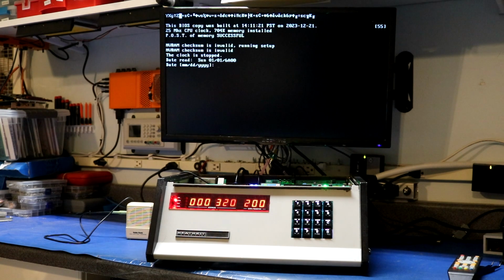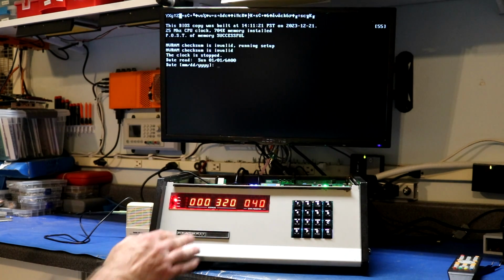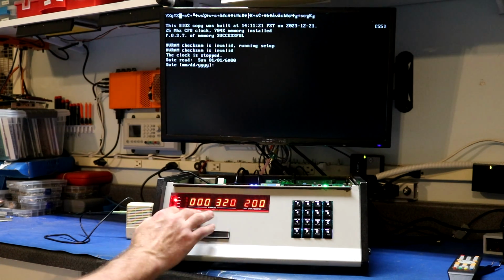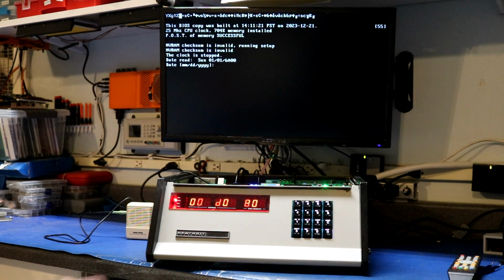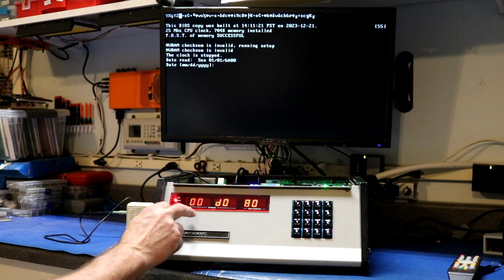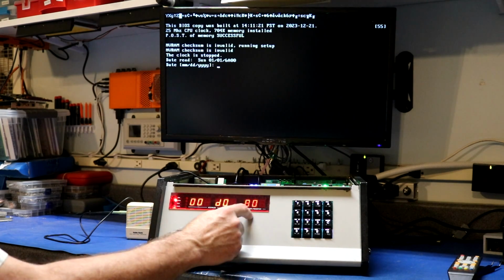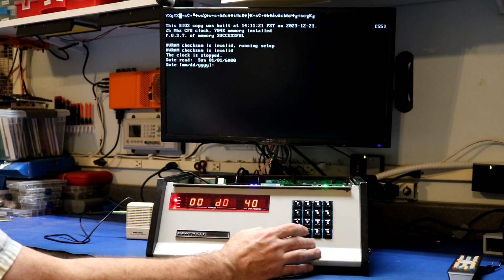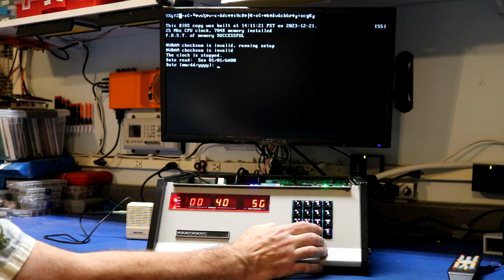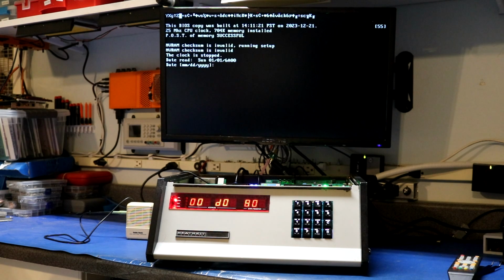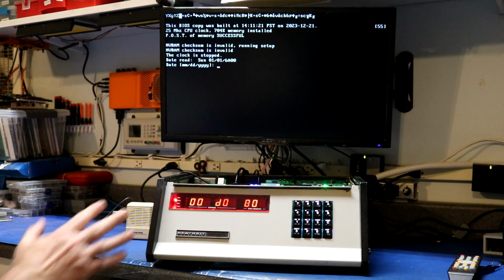I had to implement this from scratch because obviously the one for the 8080 doesn't work on the 8086. The radix is currently in octal, as is typical of Heathkit. I can switch it over to hexadecimal. And we're looking at an area in memory. This is offset 00D0. That is the value there. Since this is an x86, we've also got a segment register, segment 40. This is actually part of the BIOS data area, down at segment 40 hex.